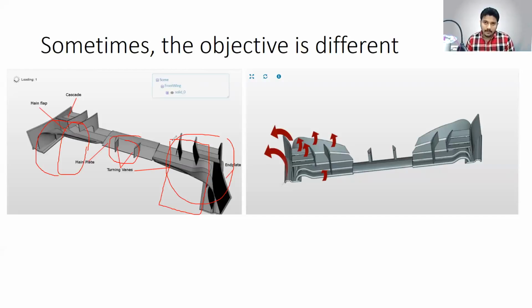The other purpose for doing this is when you're reducing the airflow to the front tires, they're not cooled very well. Okay, and one of the things that you might or might not know is, with respect to a F1 car, the braking performance improves as the temperature of the tire increases, correct? Some of you might have heard of this. And since you're not cooling the front wheels, you're actually helping it increase its temperature quite well, which means your braking performance is going to hit its maximum value quite sooner, which is good, right? Because these people drive at ridiculous speeds and they need their brakes to work as effective as possible.